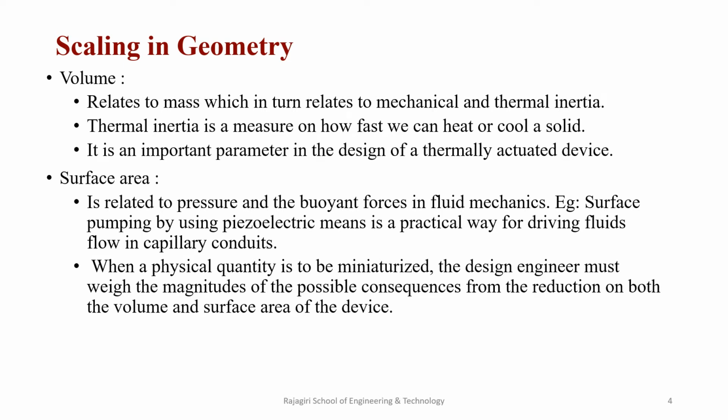Volume and surface area are two physical quantities that are frequently involved in micro-device design. Volume relates to the mass and weight of the components designed. Mass of a component, in turn, relates to both mechanical and thermal inertia. And this thermal inertia is related to the heat capacity of the solid, which is a measure of how fast we can heat or cool a solid. Such a characteristic is important in the design of a thermally actuated device.